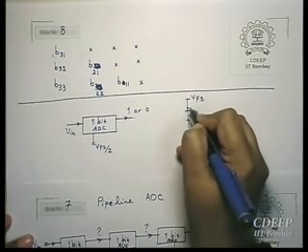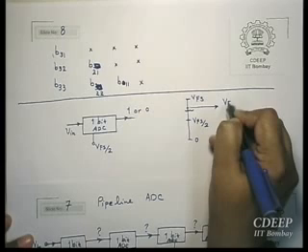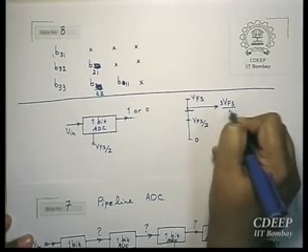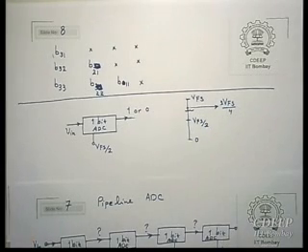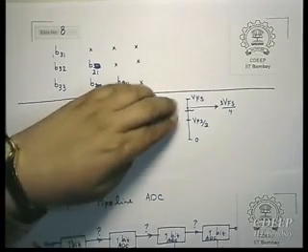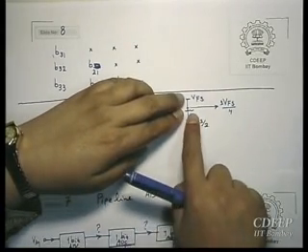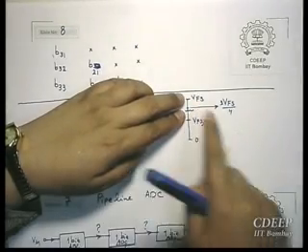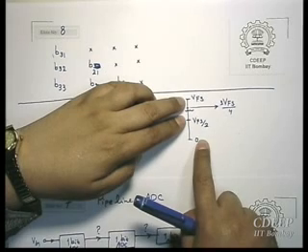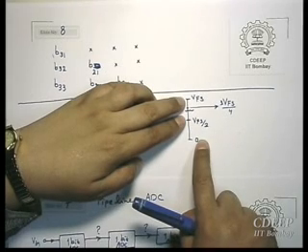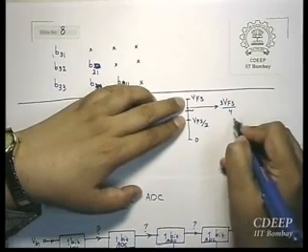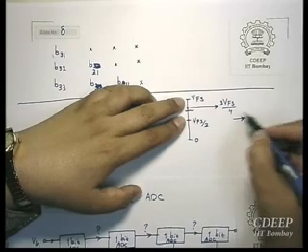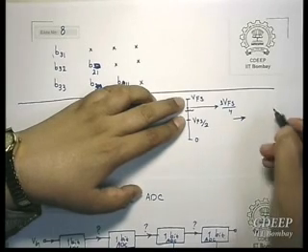To compare your input V in with 3 V full scale by 4. But we don't have any 3 V full scale by 4. This is just a 1 bit ADC. Right? So what we need to do? Now I know my input is on the second half. Now if I deduct V full scale by 2 from the input, what will I get?